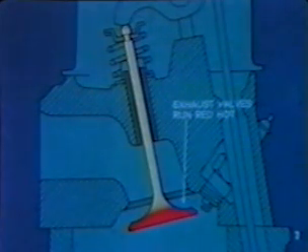Engine valves are made of a special high-strength steel that is especially heat resistant. Exhaust valves get the hottest. In fact, they operate red hot because of the heat blasts from the burned gases flowing past them. Heat is transferred from the valves in two ways, from the head to the seat, and from the stem to the guide. Obviously, it is desirable to move as much heat as possible to the stem, since its guide is in a cooler place and has a big surface available.